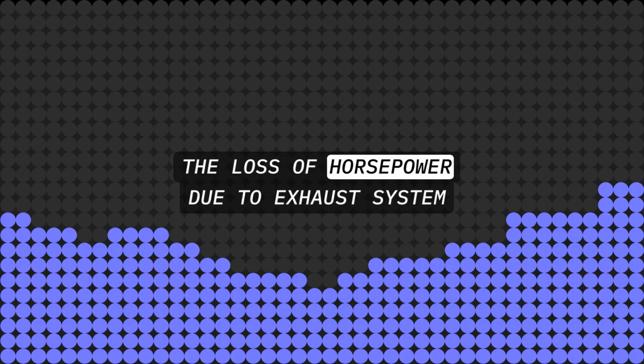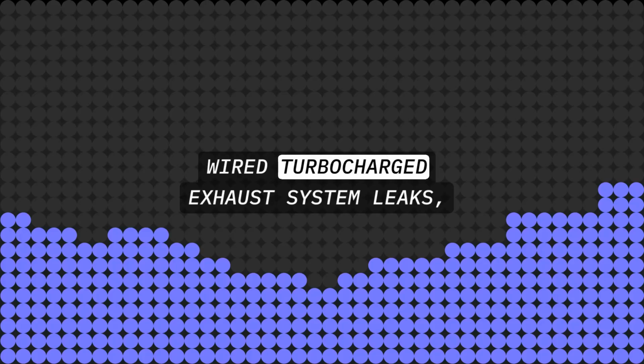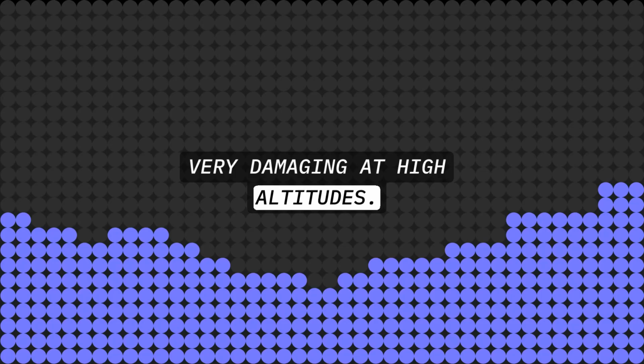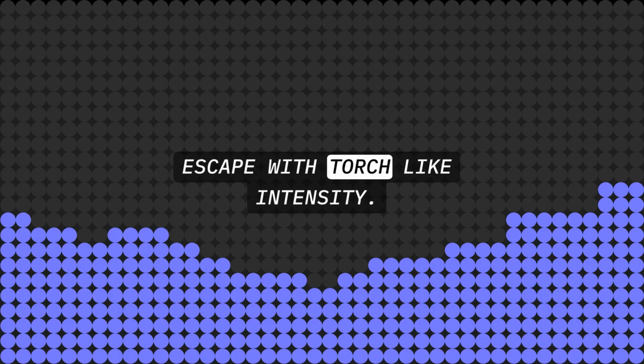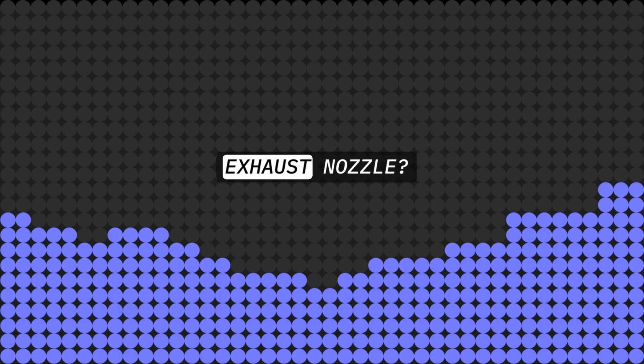What drawback in using collector type exhaust systems is more than offset when used on turbocharged engines? The loss of horsepower due to exhaust system back pressure. Why are turbocharged exhaust system leaks very damaging at high altitudes? Pressure differential will cause the leak to escape with torch-like intensity. What are the components of a typical turbine exhaust nozzle?